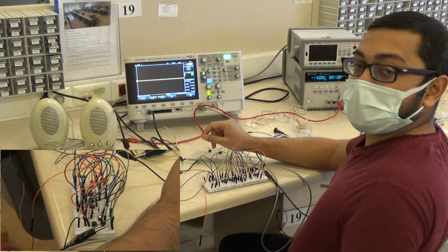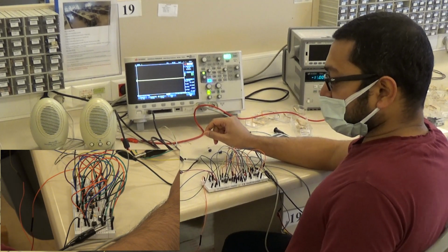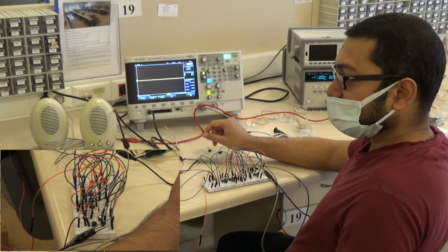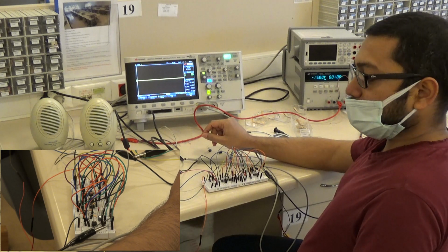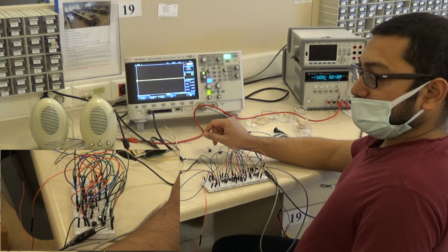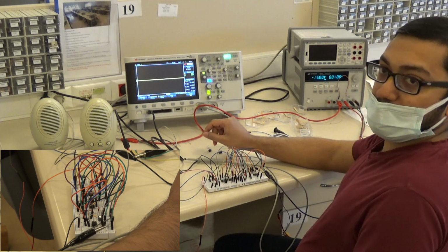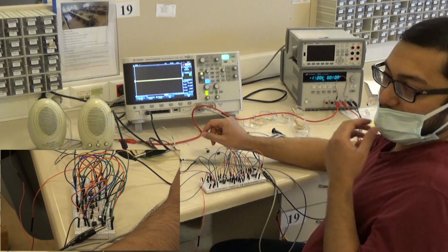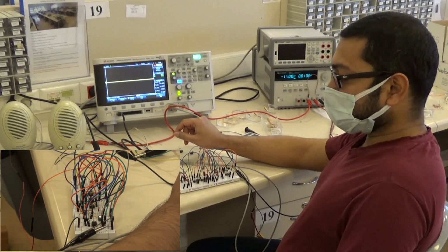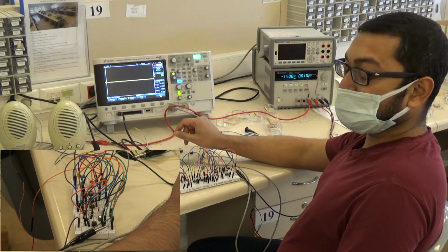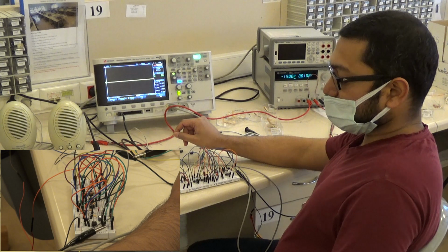Basically, we'll go to the circuit implementation for the radio lab. As I said before, in the first part of the circuit we pass an AM modulated signal, which is then connected to a band pass filter centered at 175 kilohertz, then amplified by around 60 volt per volt, then demodulated using an envelope detector or peak detector circuit.